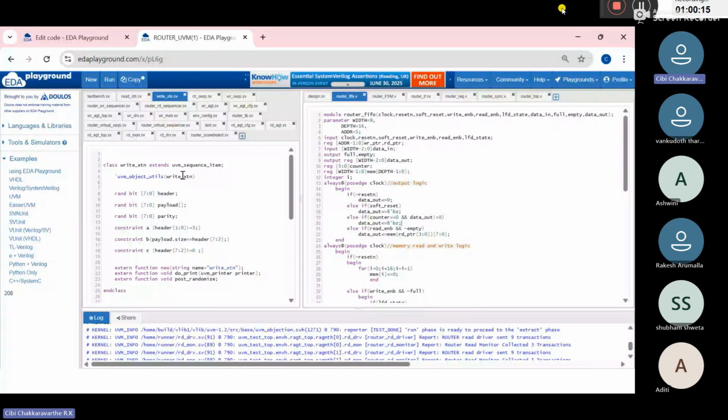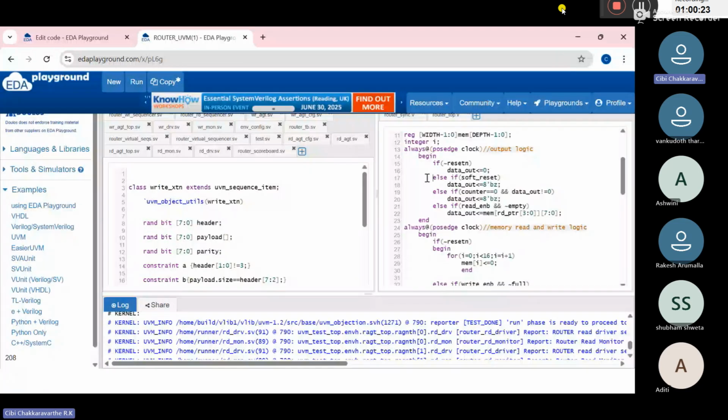If we do soft reset, see, all the bits are in high impedance state. That means it will not go to 0. Suddenly it will not be 0, but everything will be stopped. Every transaction will be stopped. Then our bus will have the connection, it will move on to the next process, it will move on to the transferring of the next data.